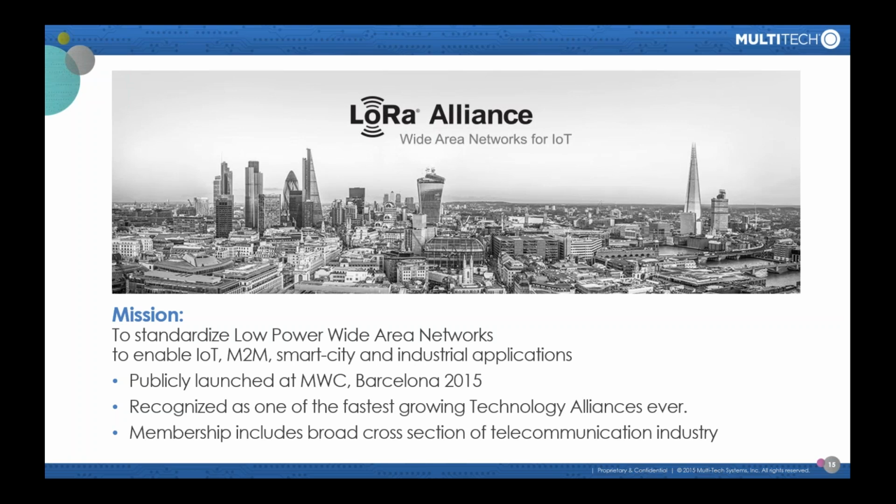It is also important to note that sometimes people get confused when they hear LoRa technology, LoRaWAN, and what are the differences. So LoRa is the technology. It is literally the chips and the technology, the modulation that enables the transfer of data. LoRaWAN is the protocol specification of how information should be sent utilizing LoRa technology. And it's the LoRaWAN specification that is the standard, managed through the LoRa Alliance and those over 500 companies to ensure that if one person manufactures LoRa endpoints, they will be compatible with other manufacturers of endpoints or gateways and vice versa. So it's a very good governing body. I'm a member of the marketing committee, and I enjoy my time with them.